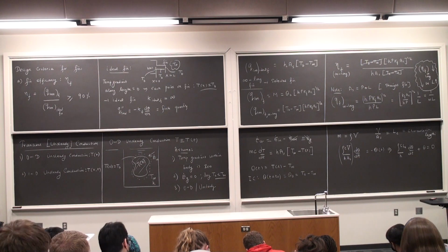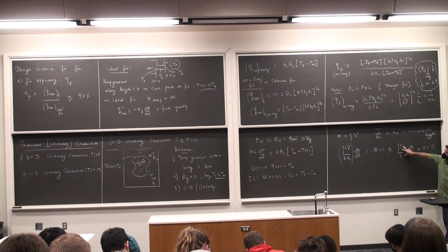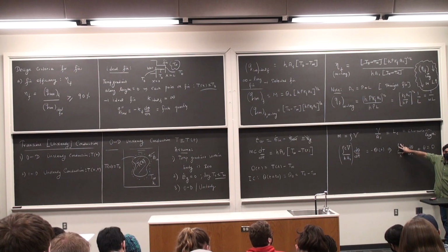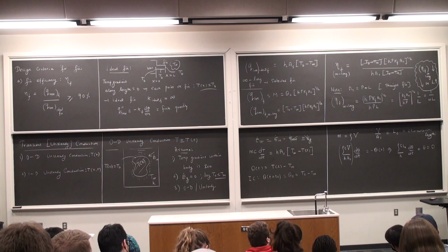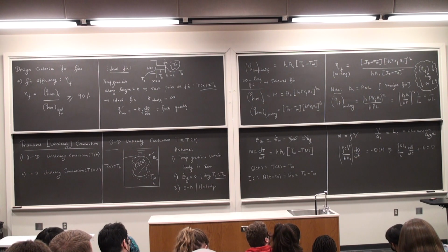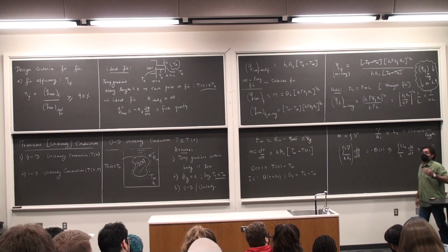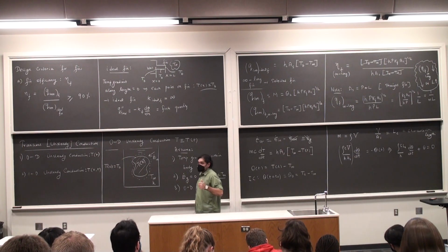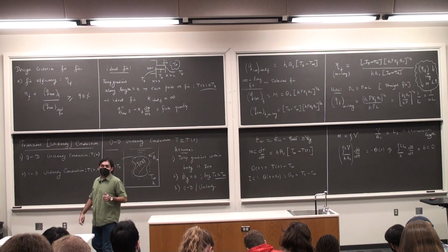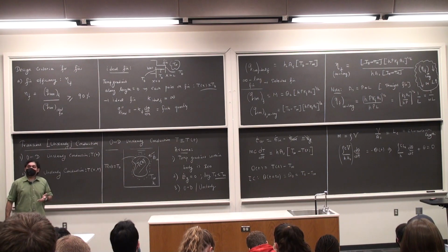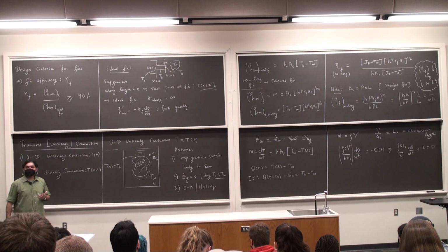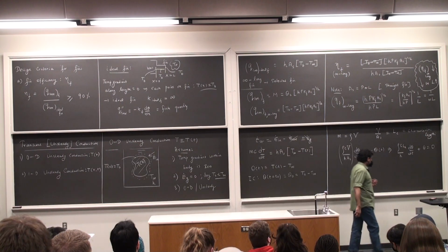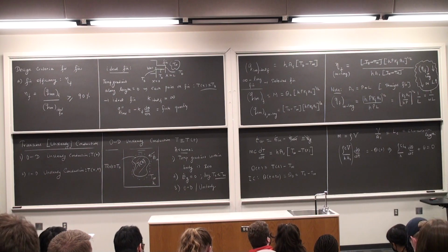System dynamics question, what do you call this quantity? The first order time constant. The fundamental characteristic of a first order system is one variable which is a time constant. If the time constant is small, the response is nimble. If the time constant is large, the response of the system is sluggish. Second order system, you have two characteristic variables, natural frequency and damping ratio. We will not come across that, of course.